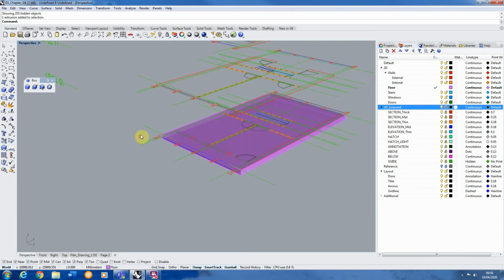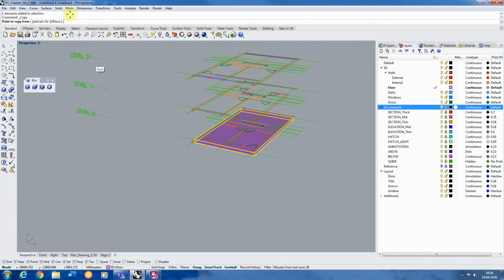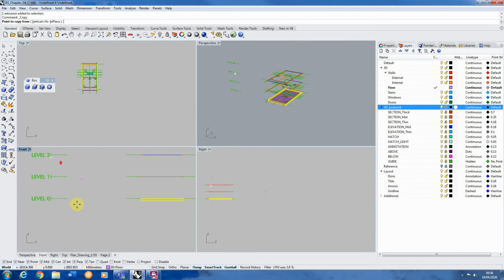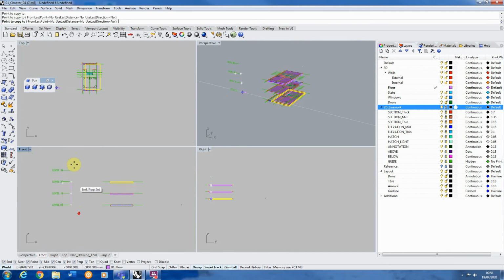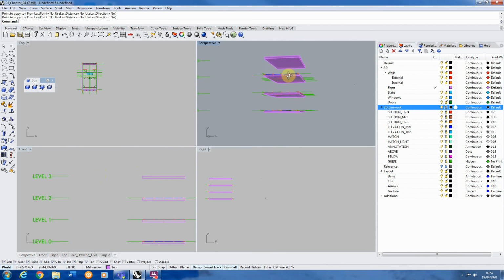So now we've modelled one floor plate, we're literally just going to use the copy tool, lock it vertically in place, or when we do this we could go back to our 4 views, go on our front view here, and we can just drag this up, hold down the shift key and snap it onto its relevant layers. And if you look as we do that, it's just copying them into place on our levels there. So now we have a floor plate on each floor, like so.